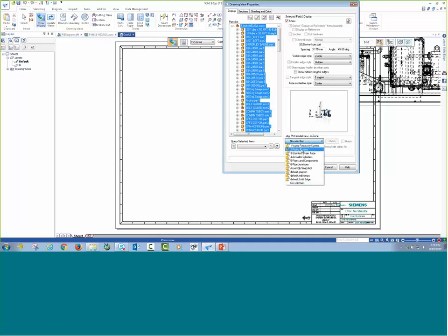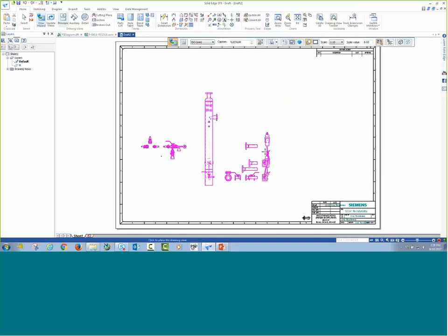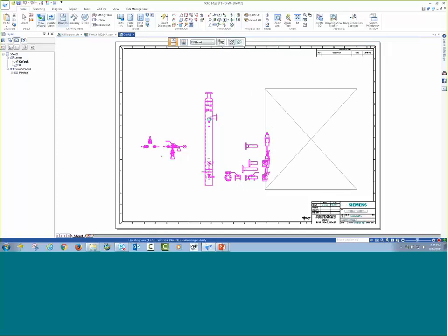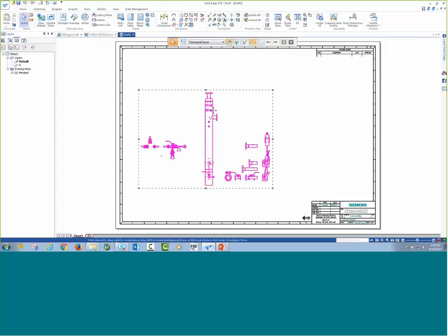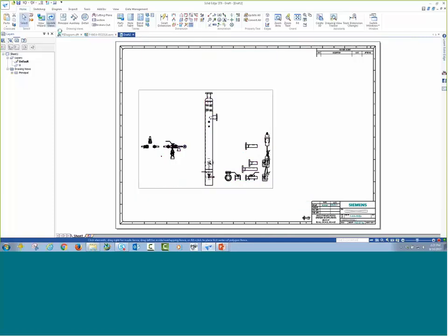And we'll go ahead and utilize that same display configuration, and then we'll place that front view right on our drawing. And actually what I want to do initially is go back through and turn those center lines on. I forgot to click that option when I placed it. Let's go ahead and specify that, and then let's update our views.